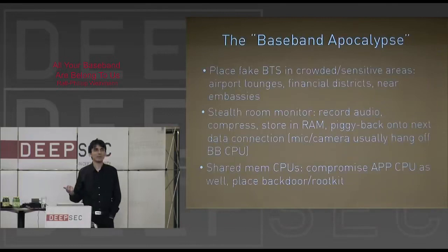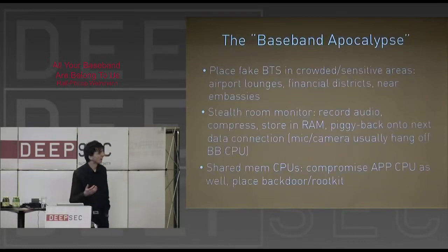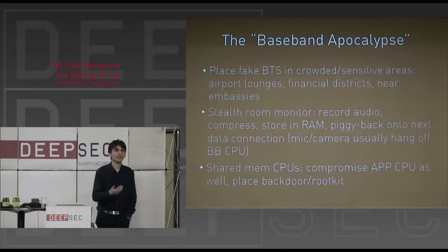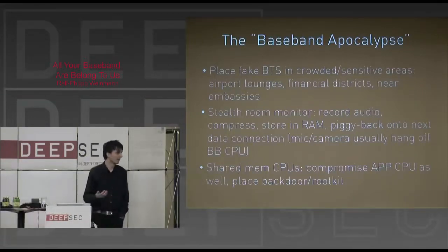Now, you have some more budget to spend on developing exploits, so you don't like this stupid auto-answer thing that's ridiculous. So you just record audio, compress it, and there's lots of RAM there. Store it in RAM, piggyback onto the next data connection, and just send it out, because the baseband controls the microphone. The application CPU cannot disconnect the microphone usually. And in lots of the newer chipsets, also the camera hangs off there. So you can have fun, depending on who you are.